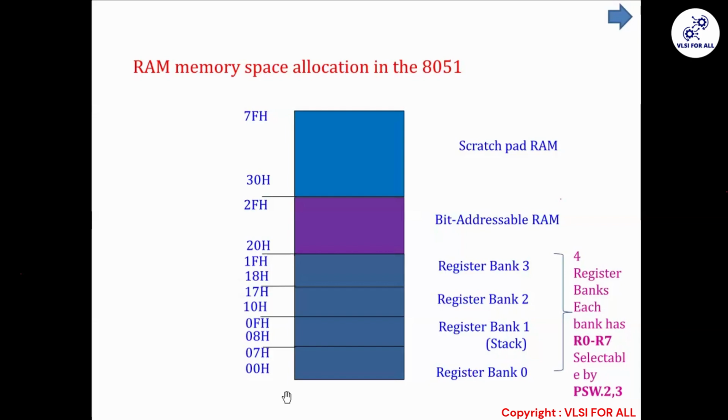This width is of 8-bit because we are dealing with 8-bit of data. Same way for register bank 1, 2, 3. In total, 4 register banks. What is the last address for register bank 3? It is 1F. After 1F, we are moving to 20.